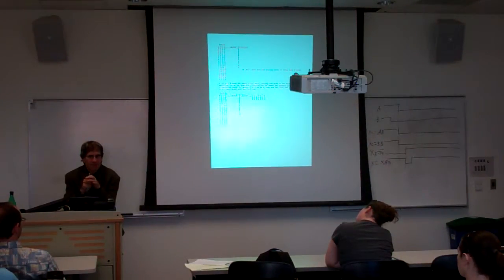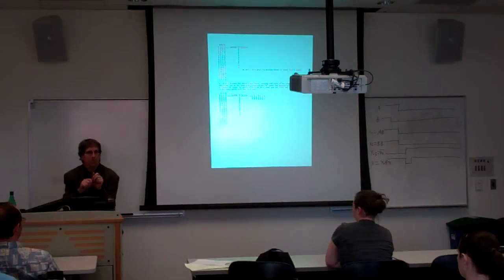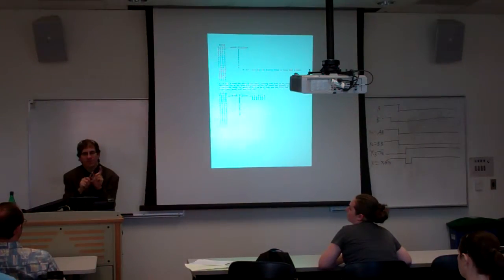And so I think you can end up with a minimal cover, the one that uses the smallest number of terms possible. And there may be more than one of those. I'd have to think about that, but I'm not sure that's actually unique. But you do want to try to get a minimal cover, which means using rectangles that are as big as possible.